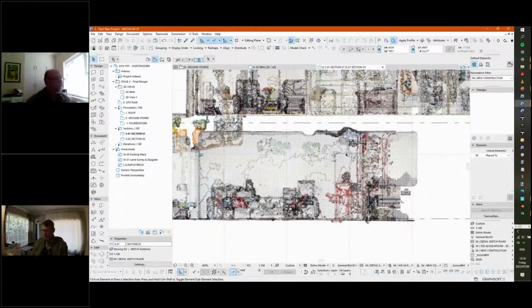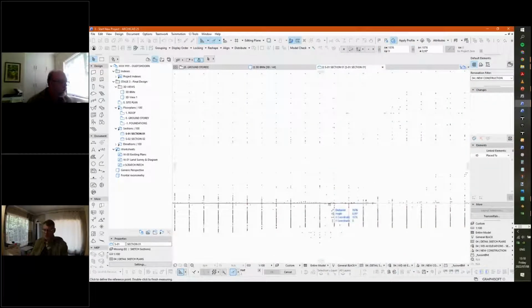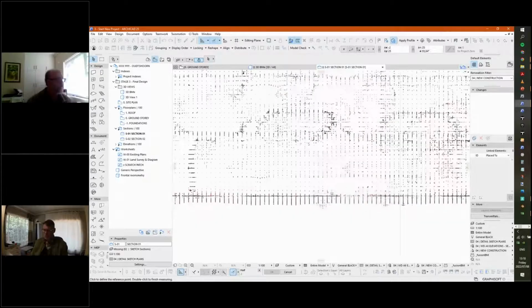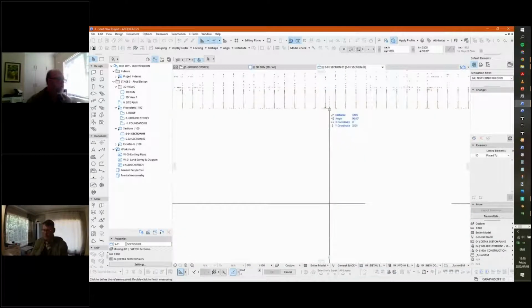In this case, we can now also start setting the story height correctly. We then measure from the story line after correct placement, and then we measure to the top floor finish there, and this tells me that the story height, floor to floor, needs to be 3205.